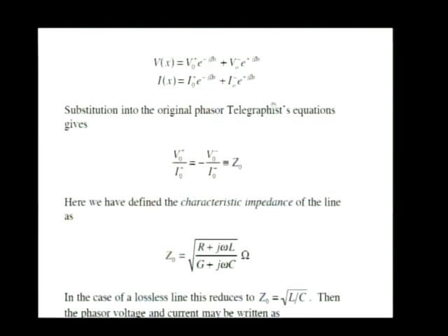They're in terms of exponentials, e to the plus and minus j beta x, times constants, arbitrary magnitude constants. Here's one constant multiplying e to the minus j beta x. Here's another constant multiplying e to the plus j beta x. And I use a complicated notation. A mathematician would usually say C1 times this solution plus C2 times that solution. That's nothing more than C1 and C2 written in fancy notation.